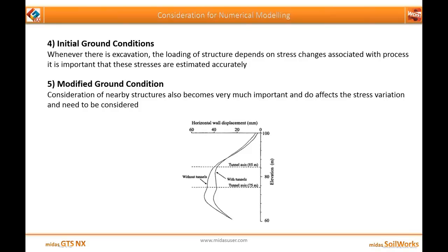Now the next thing, whenever you are doing numerical modeling, the other important parameter is the initial ground condition. Whenever there is excavation, the loading of the structure depends on the stress changes which are associated with the process. So it is very important that these stresses are estimated accurately at the beginning so that the changes which will happen during the process give us good results.